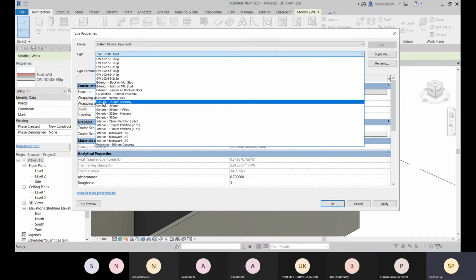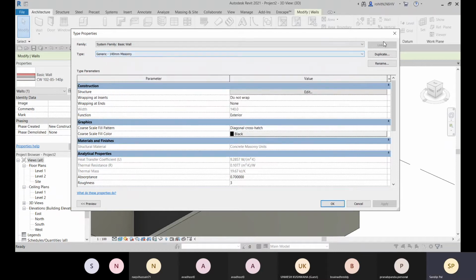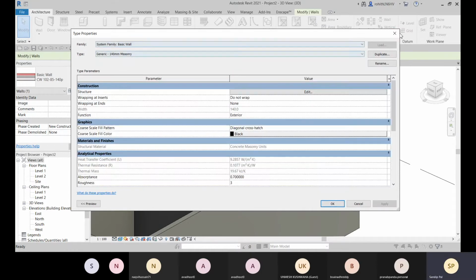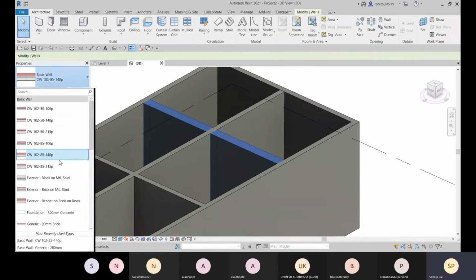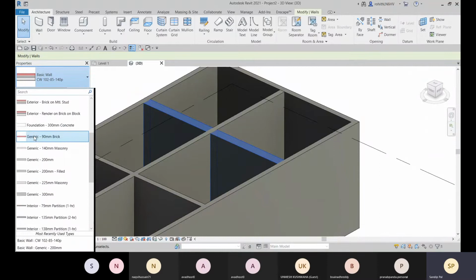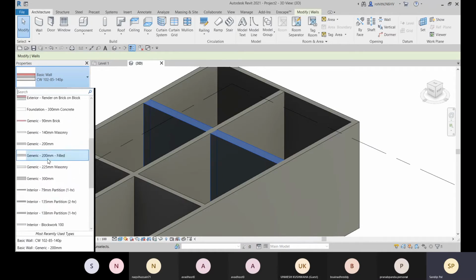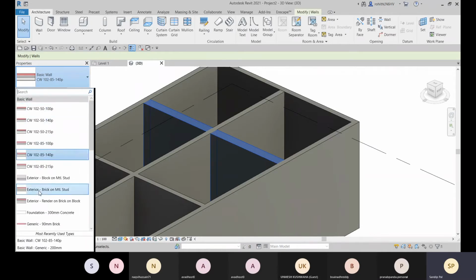and these are your generic walls. Okay, you can see. So generic wall is having one layer, and we have a stacked wall. Okay, so for this basic wall, you can see these are the basic wall. Okay, we have this curtain wall and we have this stacked wall. Okay, so we have this many type of walls. So under this basic wall, we have two types. That is generic wall and other is compound wall.